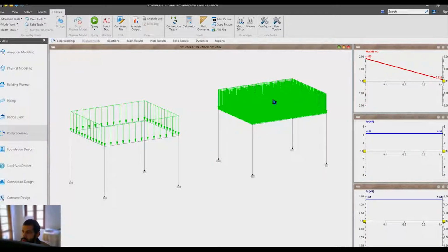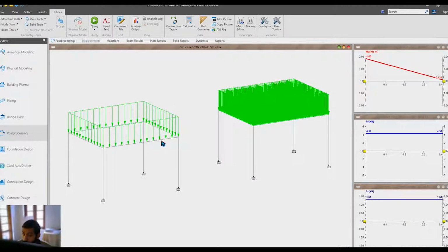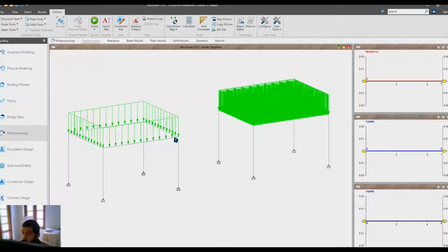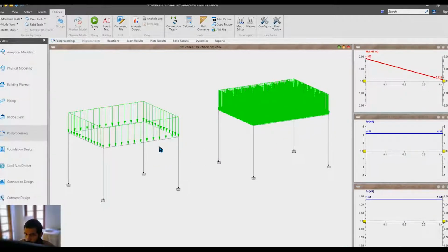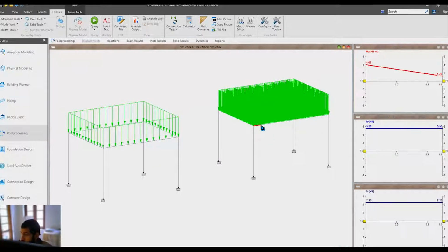We don't want to use this part. So if you want to see the whole bending, neither A nor B supports our argument. So practically this is impossible. If we put up a slab in STAAD Pro and mesh the slab, we are not going to get the proper bending moment of the beam AB, which is right here and which is divided right here.